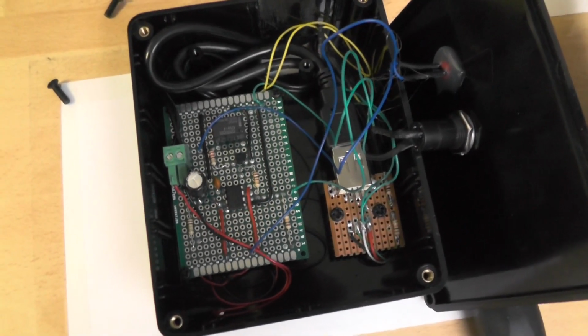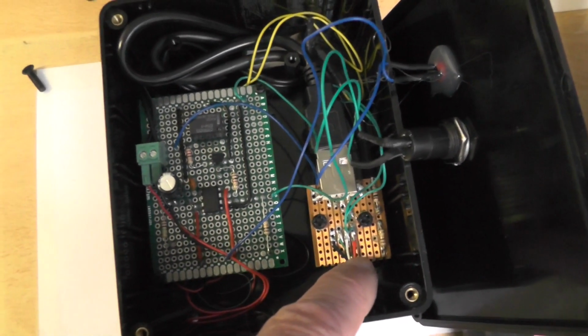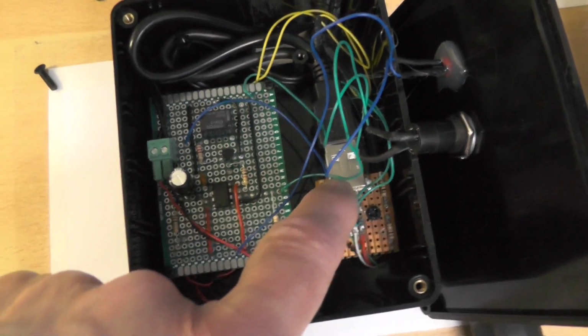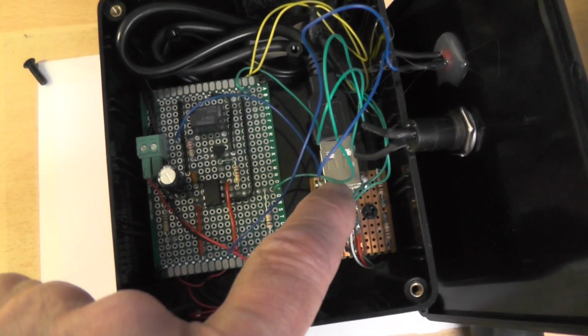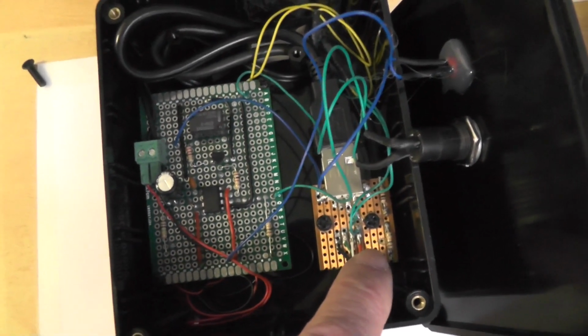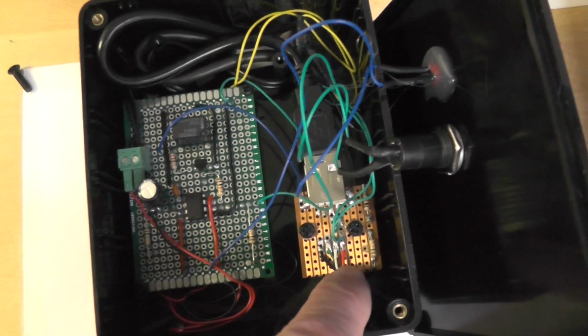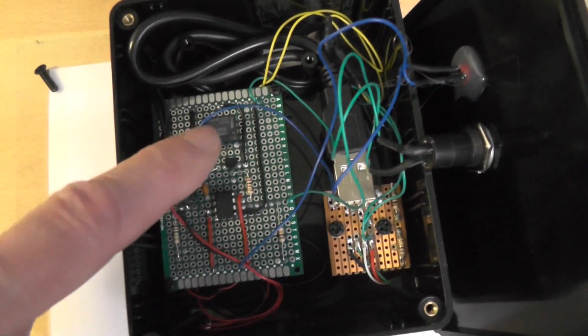Okay, this is inside the timing box. Basically, this cable goes to the USB port of the Raspberry Pi, and this USB socket here is the actual barcode scanner itself. Now on the USB, the outer pins of the USB connections are power. So what I've done is break the power to the positive side of the USB connection and feed it through to this relay here.